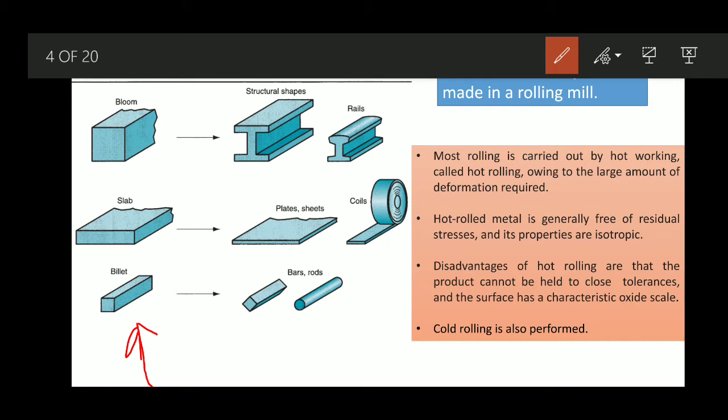Now this particular figure shows different final parts. In the previous introductory classes we discussed cold working and hot working processes, and we have seen their advantages and disadvantages. In hot working, a large amount of deformation is possible because we work at an elevated temperature and the ductility present is more. So by using somewhat less pressure or force we can get higher reduction, or higher deformation.